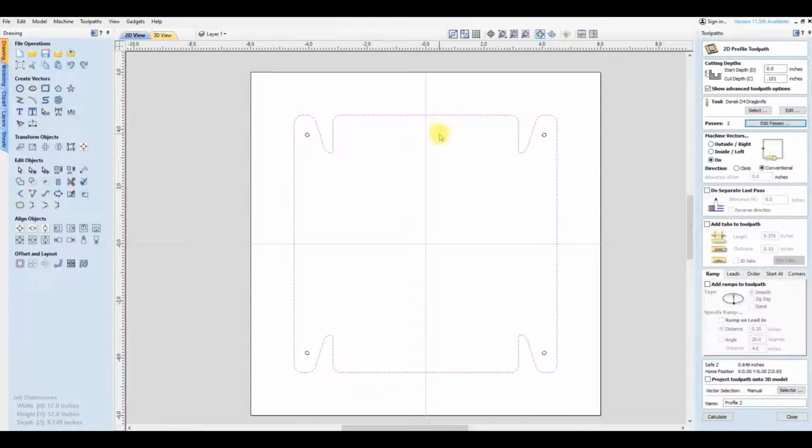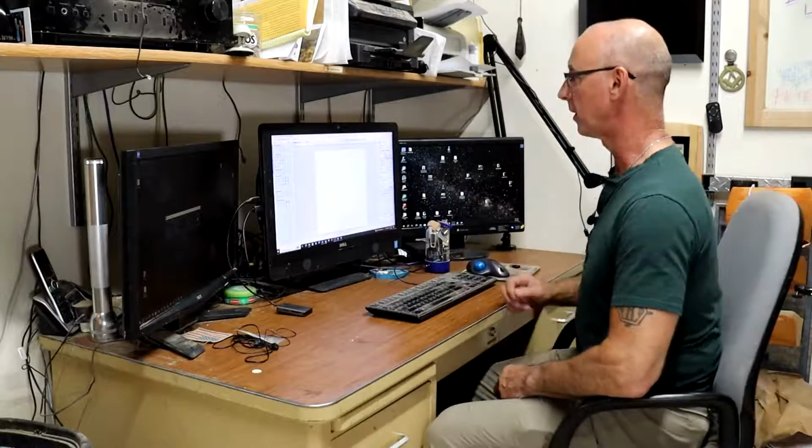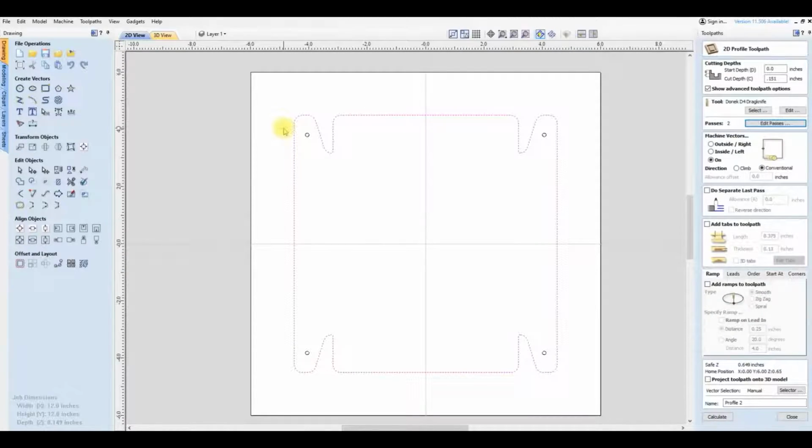Even though we've got this stuff double face taped to the spoil board, if we lighten the load and do it in 2 passes, there's less chance of that leather skating, getting pushed sideways as we're cutting on it. So let's keep it simple and do it in 2 passes. Cutting on, don't need ramps, but we do need a lead. We're going to drag knife it.